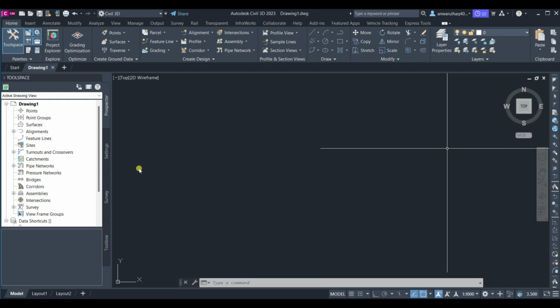If you are missing points, then we will tell you how to take the contour lines and convert them into a Civil 3D surface. First remember that Civil 3D supports Civil 3D files, and each and every CAD file can be opened by Civil 3D, but you need to convert it into a Civil 3D file first. So we start with the interface.